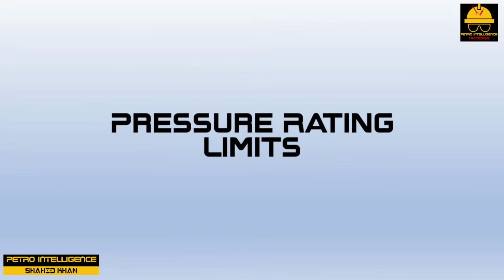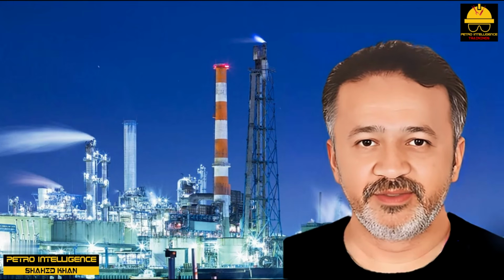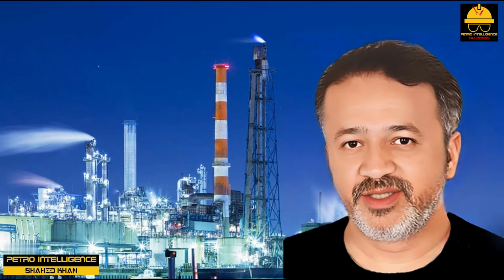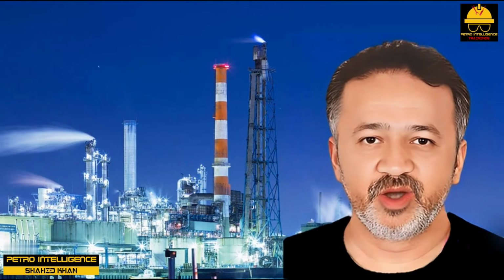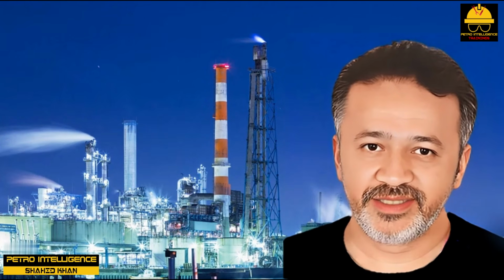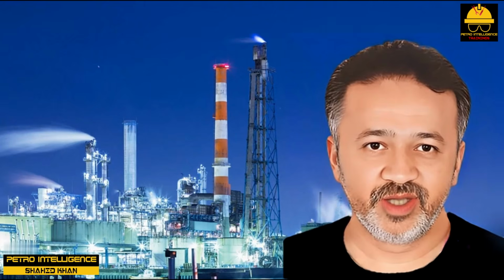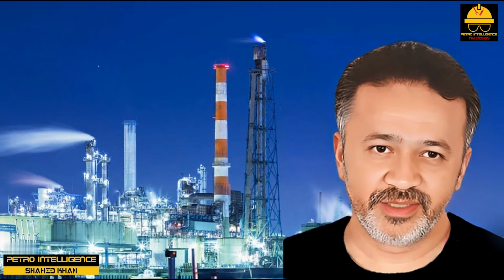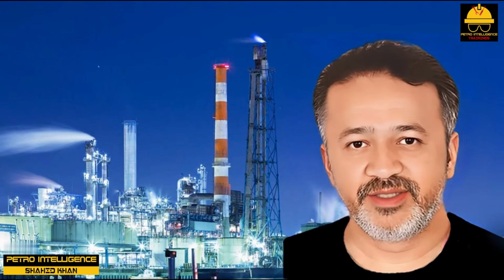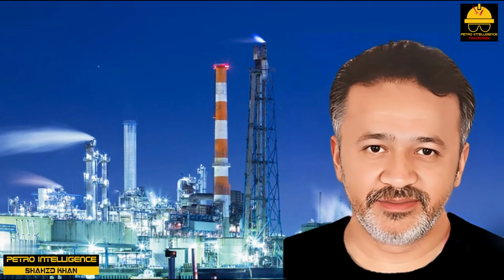Pressure rating limits. The simplest way to lower the compressor discharge pressure is to reduce the cooling water temperature to the condenser. One trick is to use the cooling tower makeup water on a once-through basis to the refrigerant condensers. This supply of water is almost always 10 to 20 degrees Fahrenheit cooler than the cooling water supply.